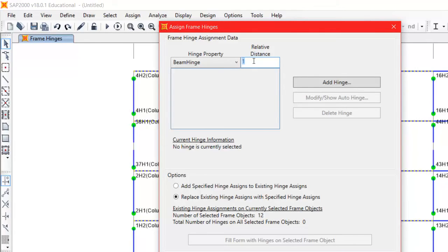Which is, I don't know, 0.6 something d or something, I don't remember, of the depth of the beam. So you have this parameter a, and then you add half the depth of the column, then you have this value x. Now, when you have this value x, you divide it by the length of the beam, center line to center line, then you will get the value that we need to put here, which is not 0, it will be a little bit more. How much did you say, John? 0.1? Okay, so he says 0.1. So 0.1, and the other one will be 0.9, right?